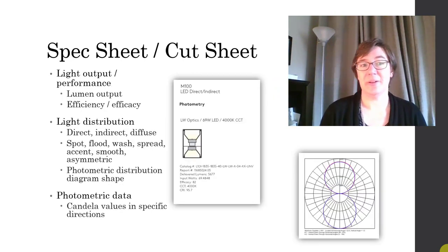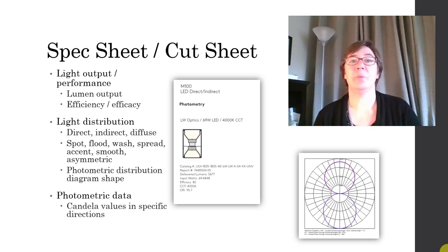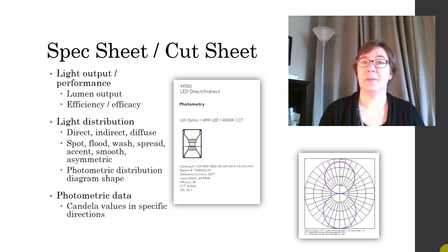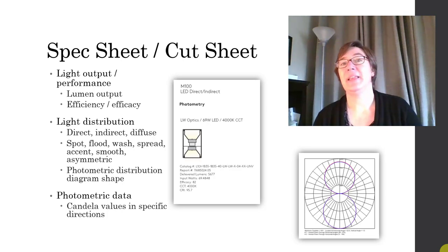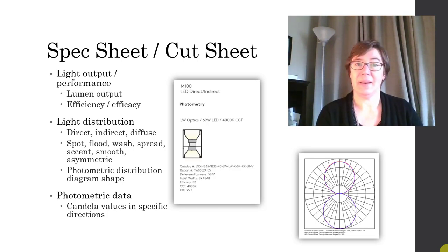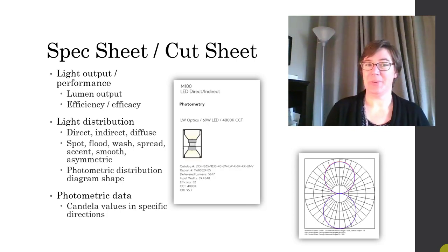The next thing you want to look at is its light output and its performance. So you'll look at the total lumen output and the efficacy of that particular fixture. Remember, efficacy is lumens provided or created per watt of energy used.